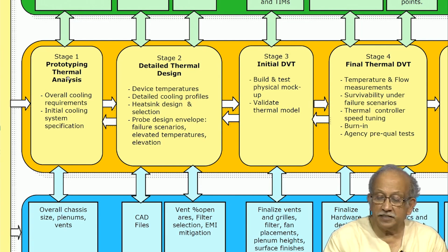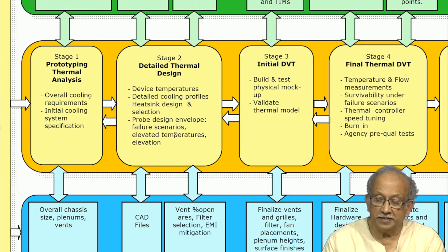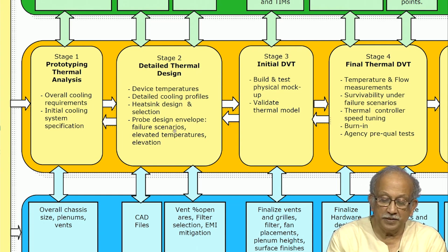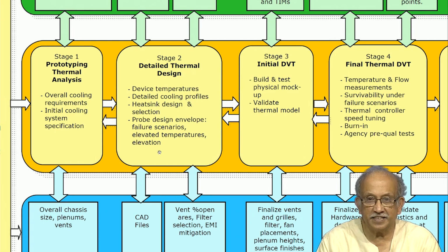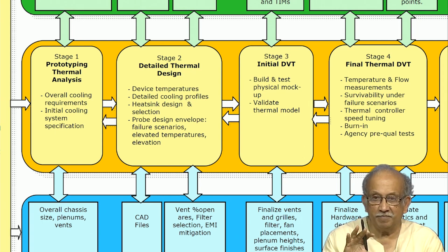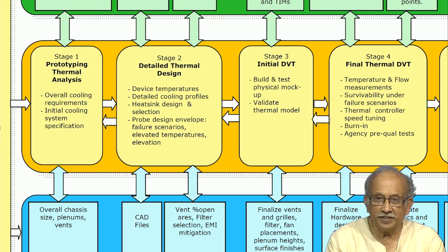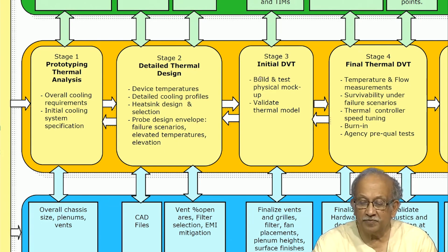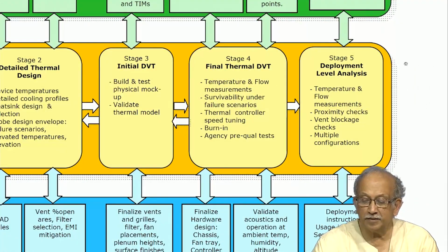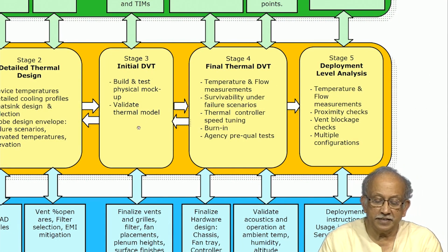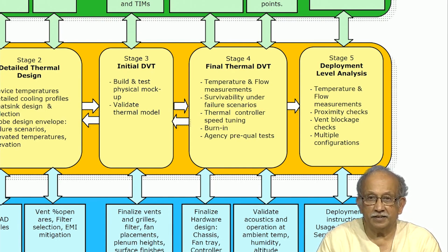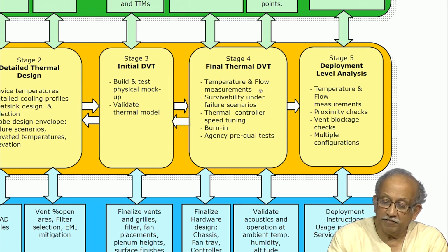This is your prototyping, the thermal analysis, then detailed thermal design, device temperatures and so on. So, probe design envelope, failure scenarios, elevated temperatures, elevations, this is critical. That is where I told you, in case you have a fully closed system, one failure leads to another. So, we build and test the physical mock-up, validate the thermal model. Thermal design validation is very important,